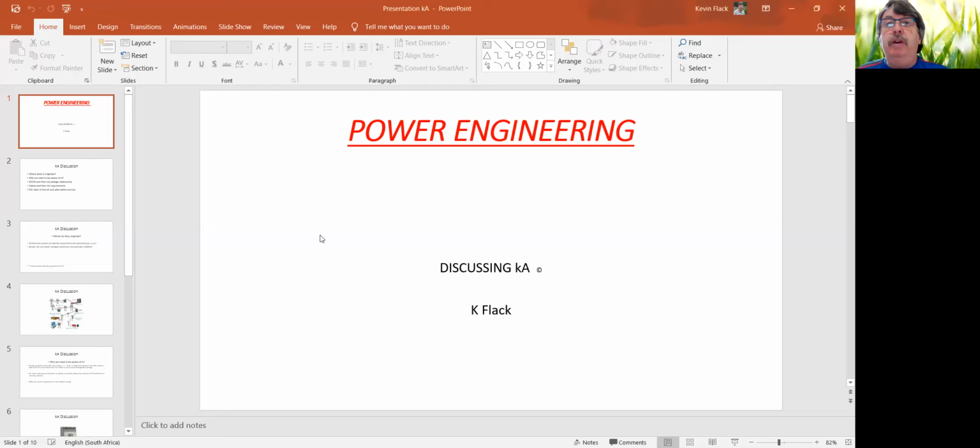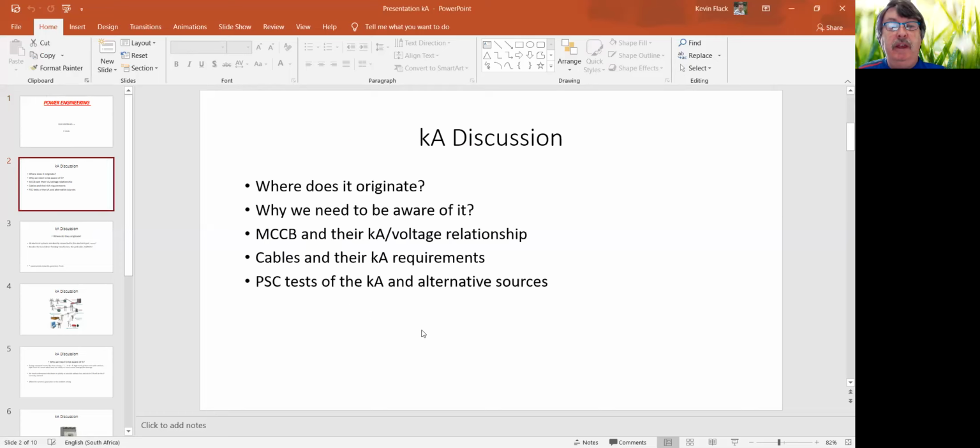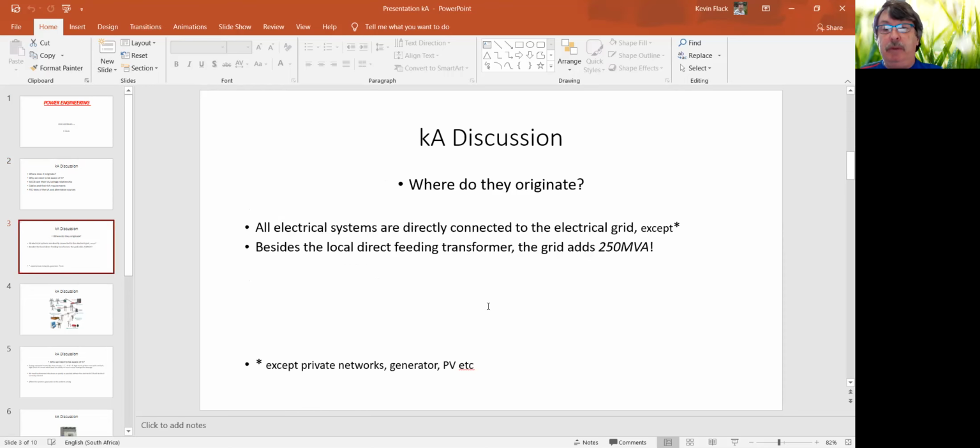this discussion. We'll be going over where it originates, why we need to be aware of it, moulded case circuit breakers and their kA voltage relationship, very important. Cables and their kA requirements, not generally discussed in great detail, and prospective short circuit tests of the kA and alternative sources. So this is a topic very close to my heart, but very misunderstood out in the electrical industry. And that's why we put it on today's topic.